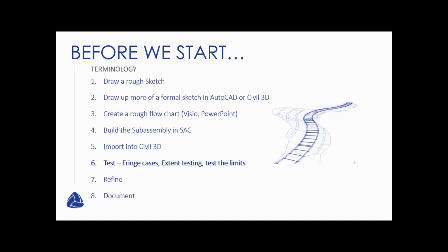Then the main idea is that it might be a rough subassembly that you compose firstly, and then you would need to actually test the subassembly. You would test it, and then essentially what we want to do is break the subassembly a bit. We want to push it to its limits. Okay. Then you would refine the subassembly. So if you've got any additional parameters or targets that you need to set up, any additional links or points that need to be defined, you can then refine the subassembly by adding those in.